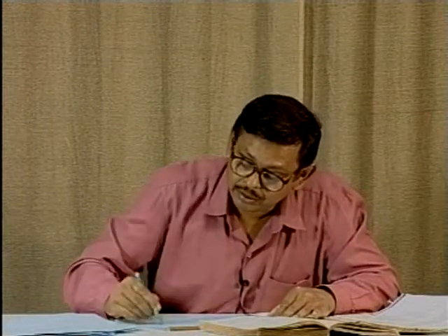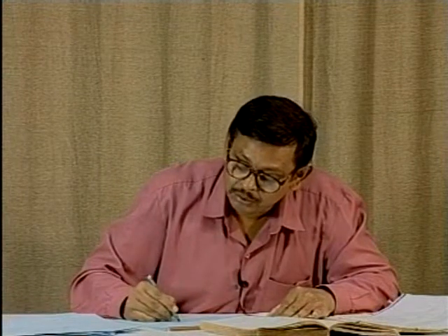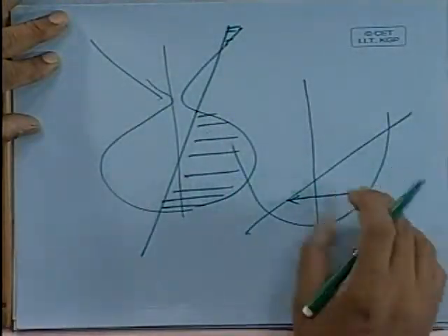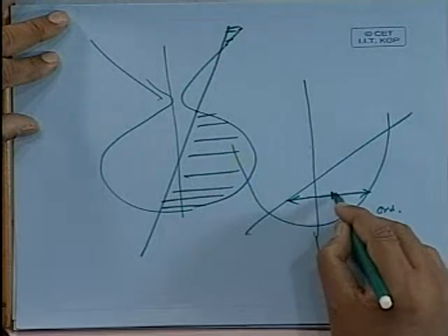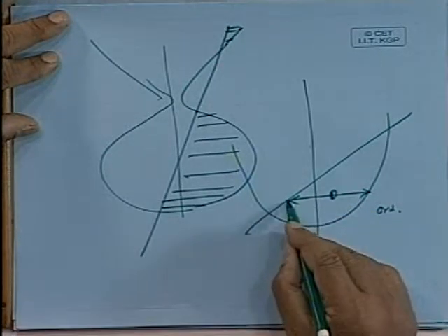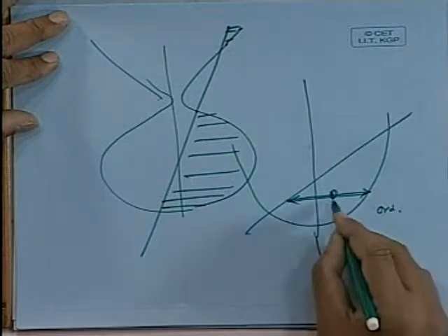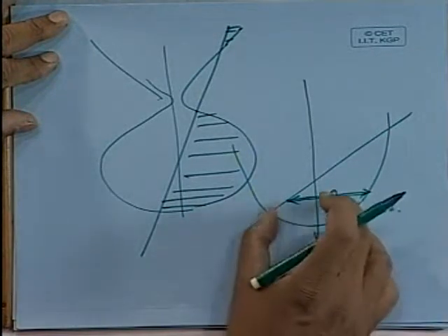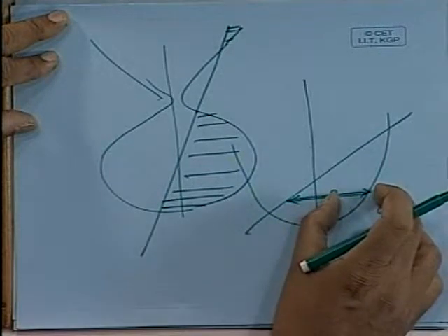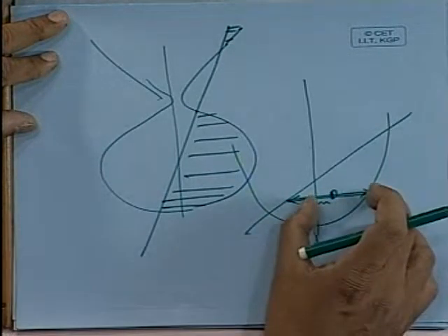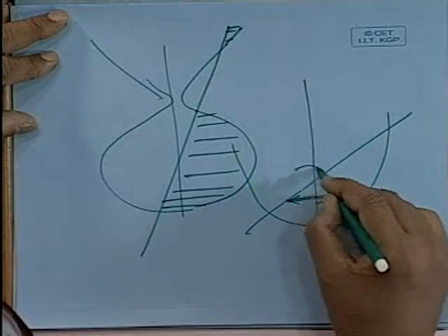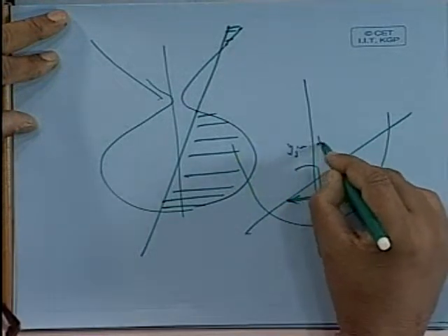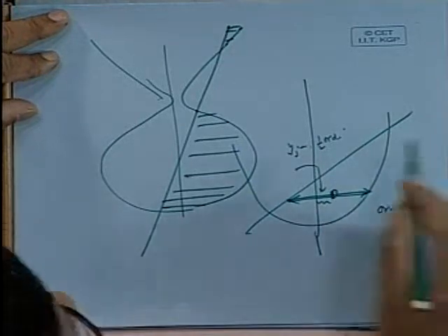Now see for the moment part. Now this is my line here. Okay. So when it is this line, I know this distance. See, this is my ordinate. Now moment about this line, the ordinate's center is going to be here. This particular ordinate will have a center at the halfway through. If this is the ordinate, then it is ordinate by 2, ordinate by 2. Okay, how much will be this much? Obviously, this is my yj minus ordinate by 2. So this distance is going to be yj minus half ordinate. Whichever way you do that, you can easily find out this halfway.